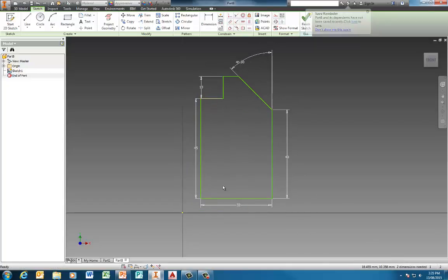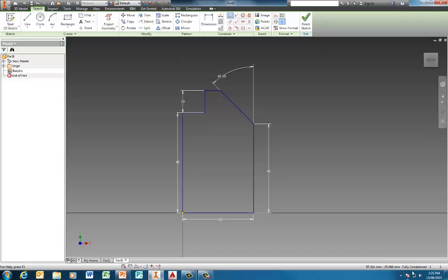Now I've deliberately left the circle feature that's going on here until towards the end of the process. So at this point I'll use the coincident constraint to constrain the object back to the origin point, which means that the sketch so far is fully constrained. But now I'll add the circle feature by using the circle command. Pick a center point, making sure it's not automatically aligned, and